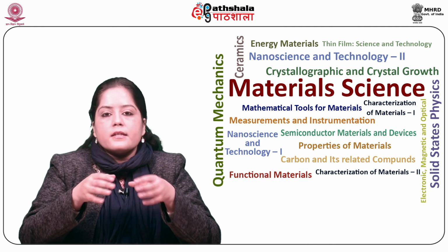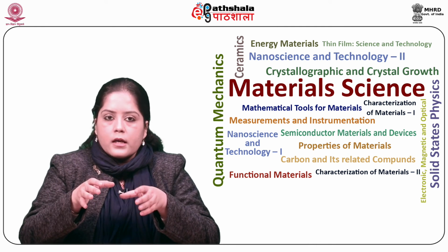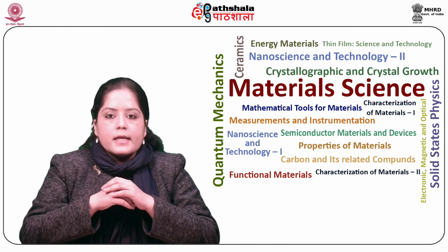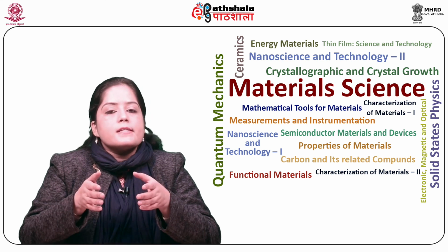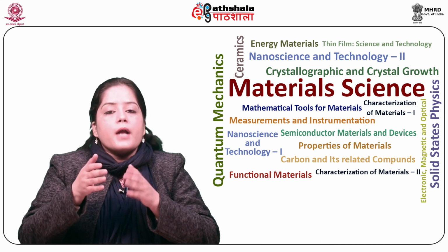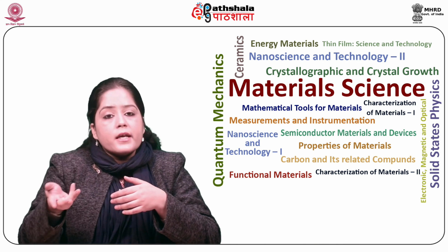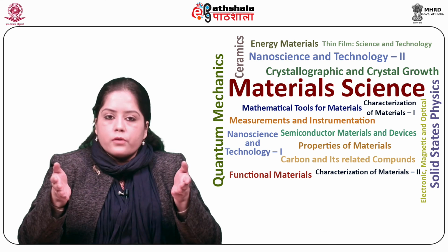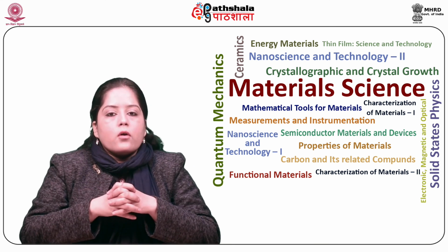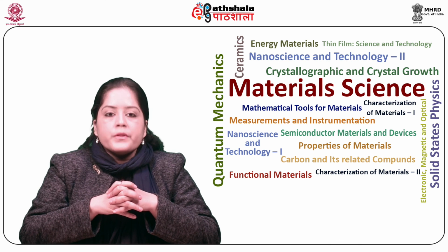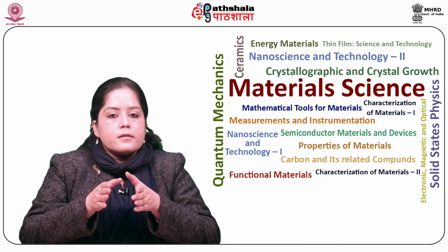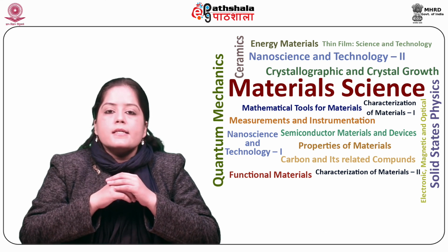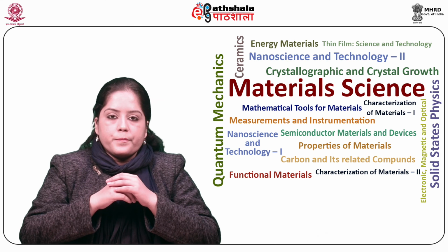Processes to fabricate nanostructured materials from atoms involve transformation processes in solutions, for example, the sol-gel technique, plasma synthesis, spraying, chemical and physical vapor depositions, etc. Availability of starting materials, often termed the precursor, is a critical aspect in nanoparticle synthesis processes.